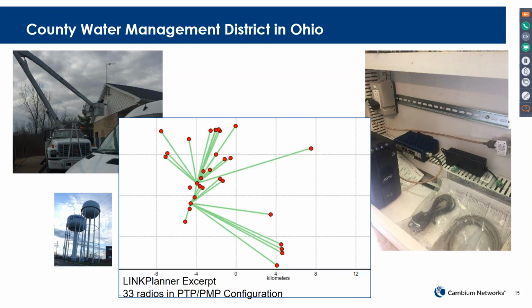This particular customer was using 900 megahertz unlicensed, and interestingly, they have a traditional interface for the RTU, so it's a serial line-based interface. So they're happy to have this cnReach because we have a serial to IP converter, which allows the serial interface data to be converted to IP. So now they can achieve all IP-based control.